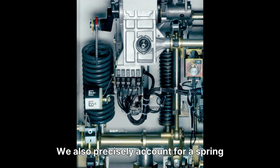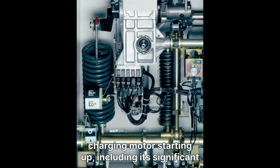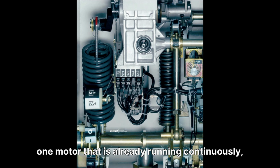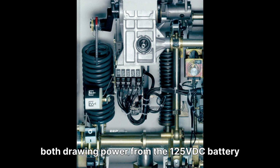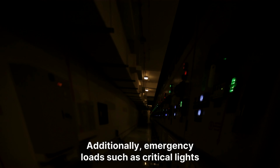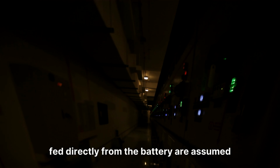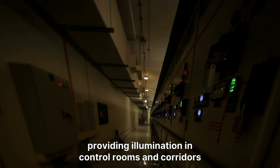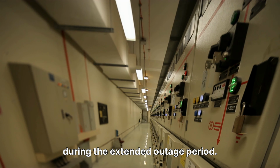We also precisely account for a spring charging motor starting up, including its significant inrush current during startup, as well as one motor that is already running continuously, both drawing power from the 125 VDC battery during this phase. Additionally, emergency loads such as critical lights fed directly from the battery are assumed to operate for a full 3 hours, providing illumination in control rooms and corridors during the extended outage period.